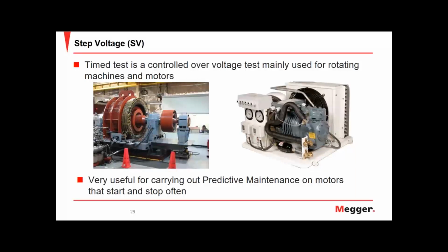It's very useful for carrying out predictive maintenance on motors that stop and start often, so they get exposed to greater starting currents and voltages. So the step test is very good for them.